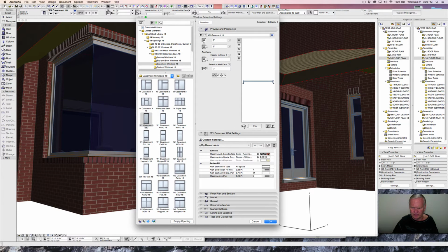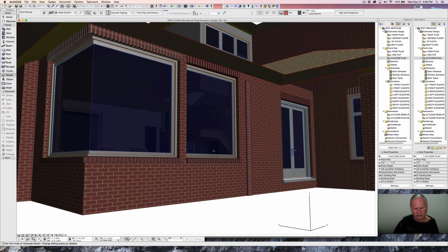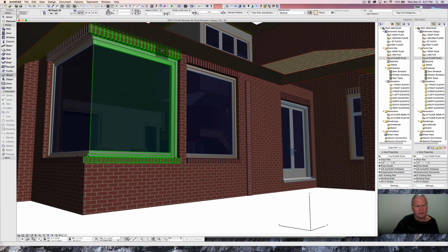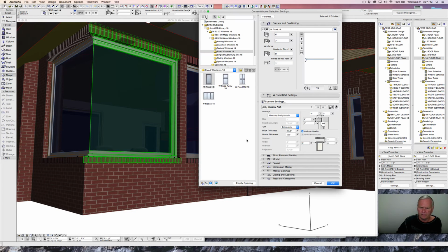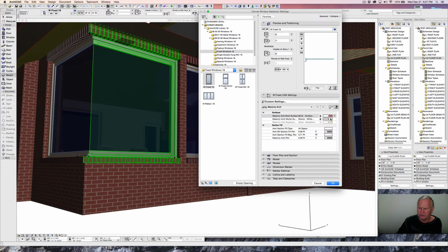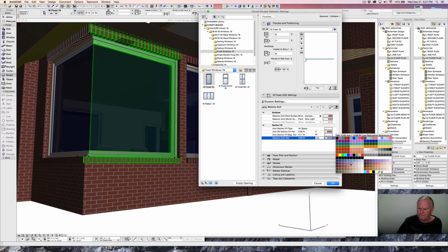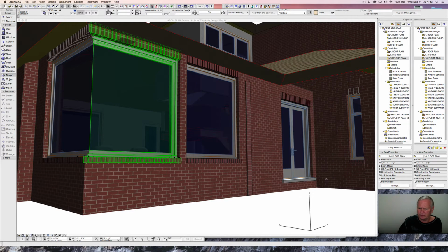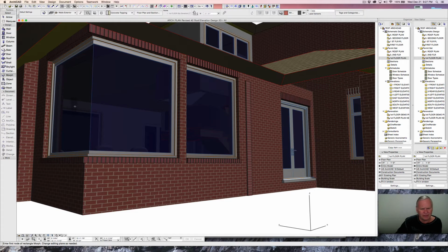And let's go take a look at our surfaces, surface color, the light gray and the black pen, and we've got that, and that should show up correctly, and it does. So this corner window looks like we need to fix that 3D aspect on that masonry arch, and that's under that setting there, and sure enough that needs to be set to that surface color, again the light gray, and our pen at 141, and now we've got that shown correctly.